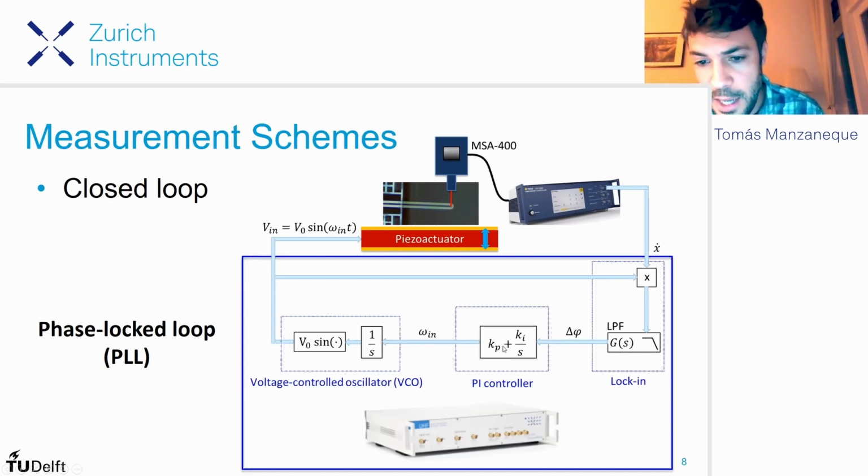So if we properly select these proportional and integral constants, and there are some publications that describe how to select them, we'll have a properly designed phase lock loop, and then this will continuously track the resonance frequency of the resonator, and then we have a sensor with a very large measurement range, right? Because this can still measure even if the resonance frequency shift is large.